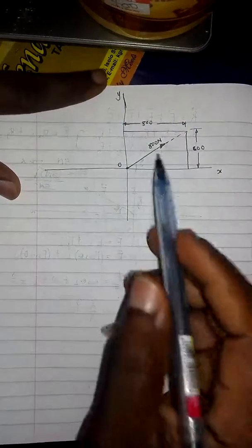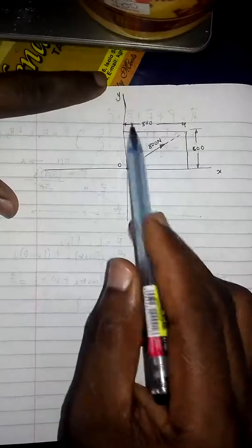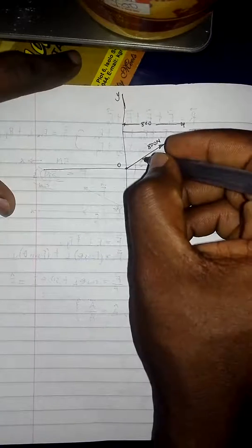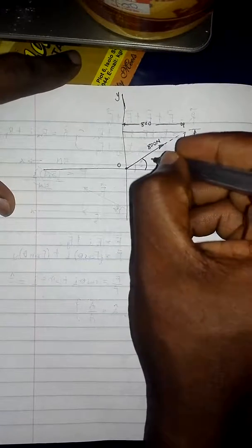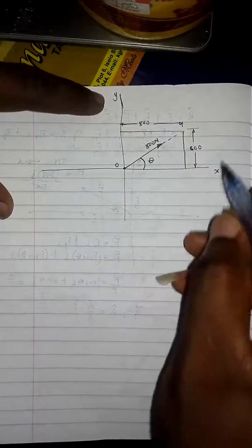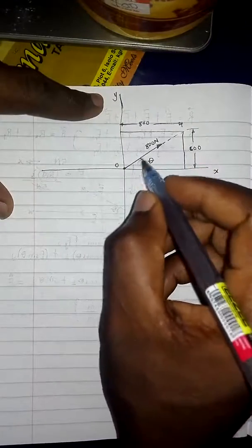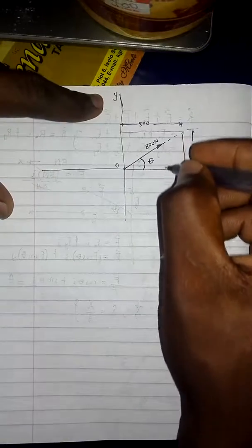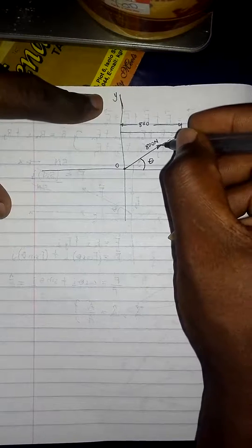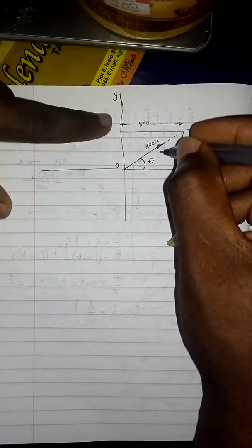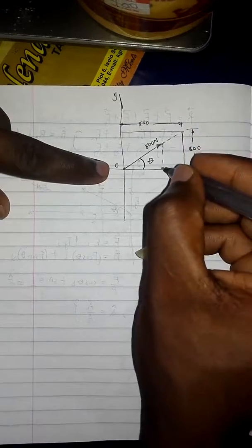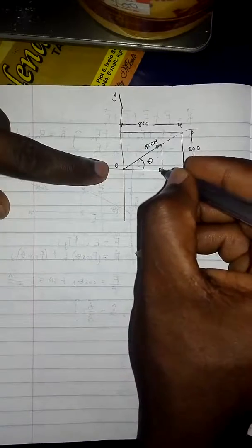So we want to get the x component of this force and its y component. So how do we go about that? So I said for you to proceed, you probably want to get the angle here. It's fine if you do. This is some angle theta, say. So from here you can say that the x component of this force, if you are going to resolve this into the x-axis, can you remember how to resolve? You project from the tip of this a line parallel to the y-axis. So you go this way, parallel to the y-axis. So that's going to be something like this. So this is going to be the line.